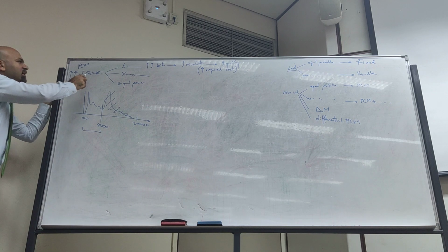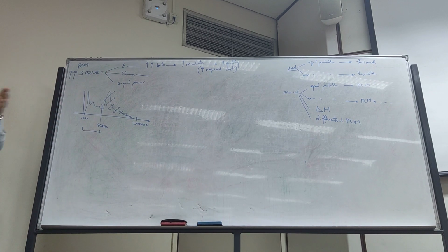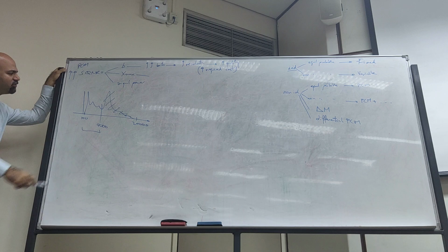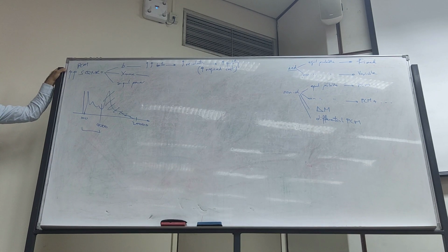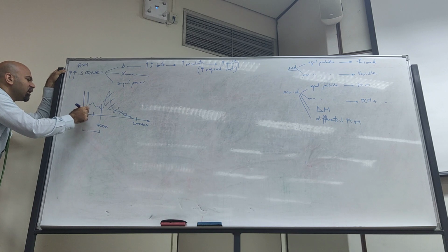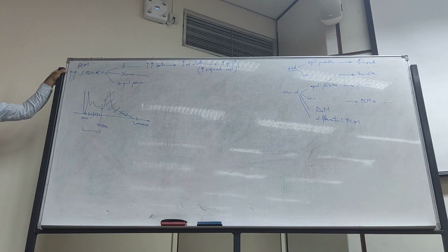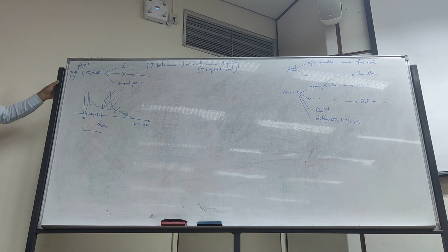This is why with the SQNR, the lower the X max, or the lower the range, you will have better performance. Also, if you have only, let's say, 8 quantization levels, you can put them like this. If you have to spread the 8 over the whole range, then the steps will be far away from each other. Clear? The last one, any questions so far?